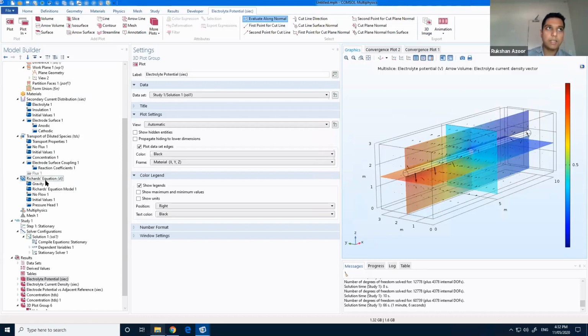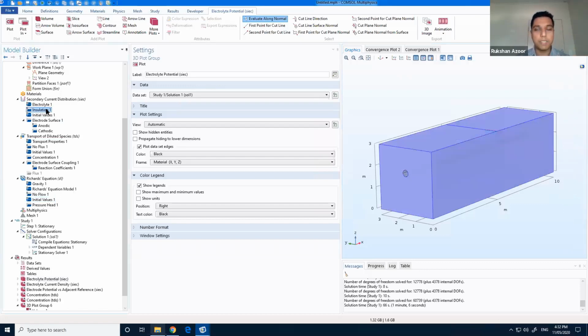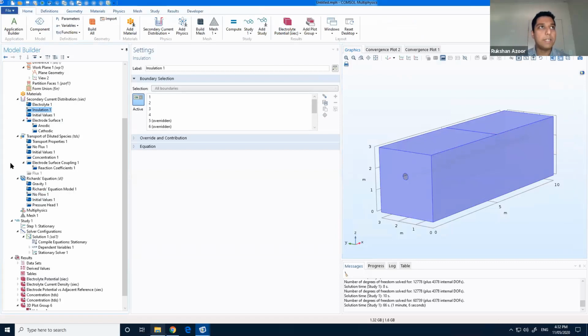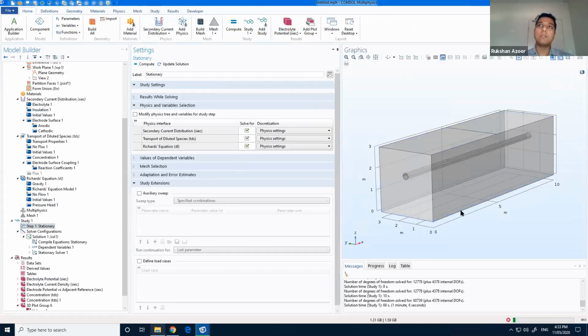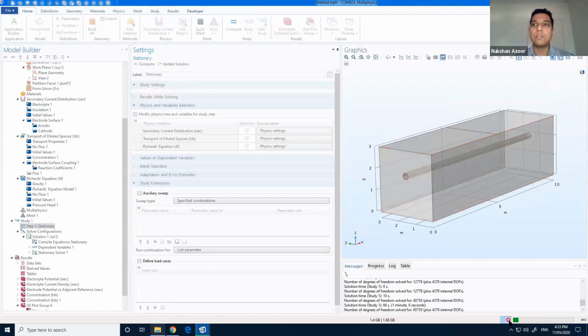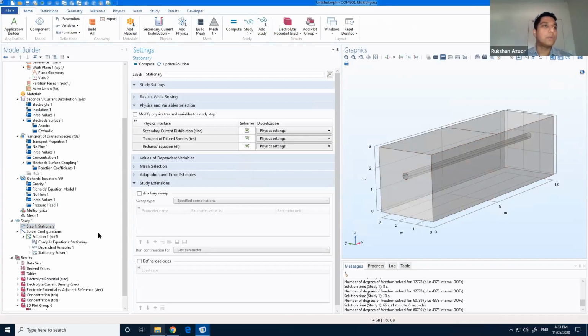Based on that suction and the gravity, the hydrostatic gradient, we look at the water retention curve and find the degree of saturation distribution in soil, and use that degree of saturation to define our transport properties and our corrosion properties. So all in all, we have three types of physics that are coupled with each other, solving one common problem. I don't have to solve this again. One physics problem.